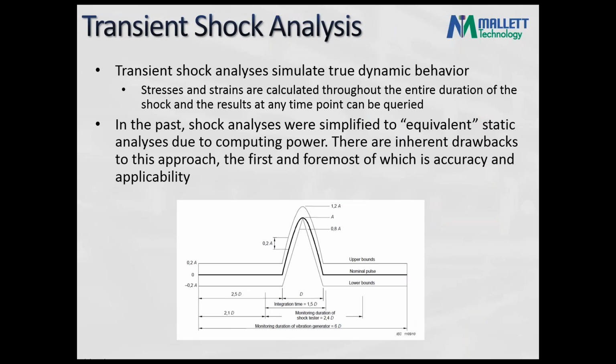Okay, so this is the last topic before anyone has any questions. The transient shock analysis, I just want to touch on this. The key I want to point out here is, especially here at Mallett, we're very large proponents of running true transient shock analyses. What this means is that we simulate everything in time, right? We take a period of time, we simulate exactly what would occur in the actual test scenario, right? So we'll start off, get the solution to steady state, and then have a shock event that occurs over the exact amount of time the true shock event would, and at each time point through that event, we'll be able to extract stresses and strains and any other data you might be interested in.